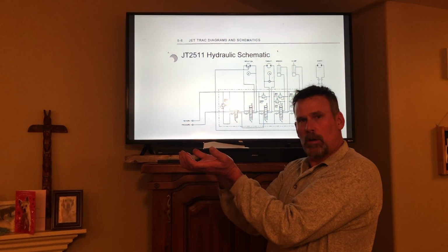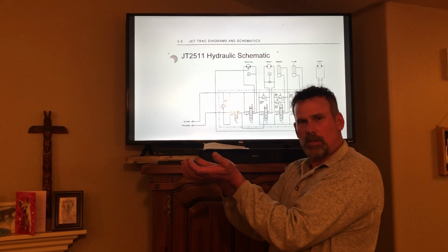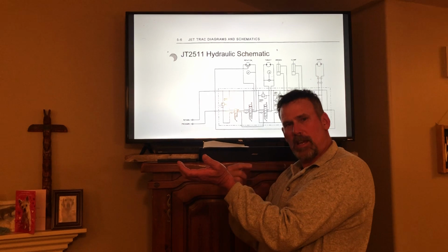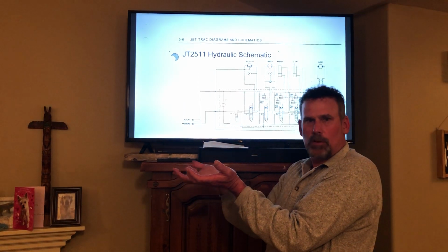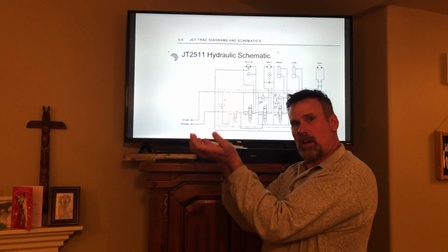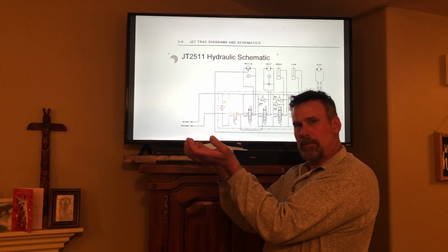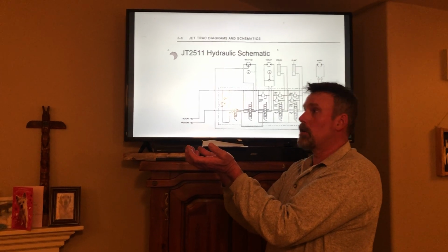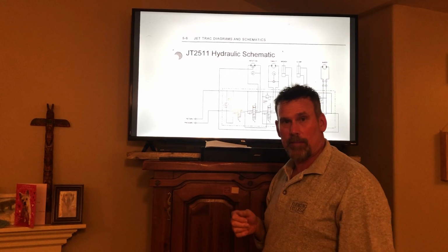Well, now, okay, I was driving over there, and it's an open center system, so the pump oil that was rotating through back to tank was at basically 0 psi. Open center system, 0 psi when it's in neutral. But I had 2,000 psi stuck in the base end of those cylinders holding that gravel up. So I get over to the dump truck and I decide, okay, I have to lift it up higher to get over the side of the dump truck.